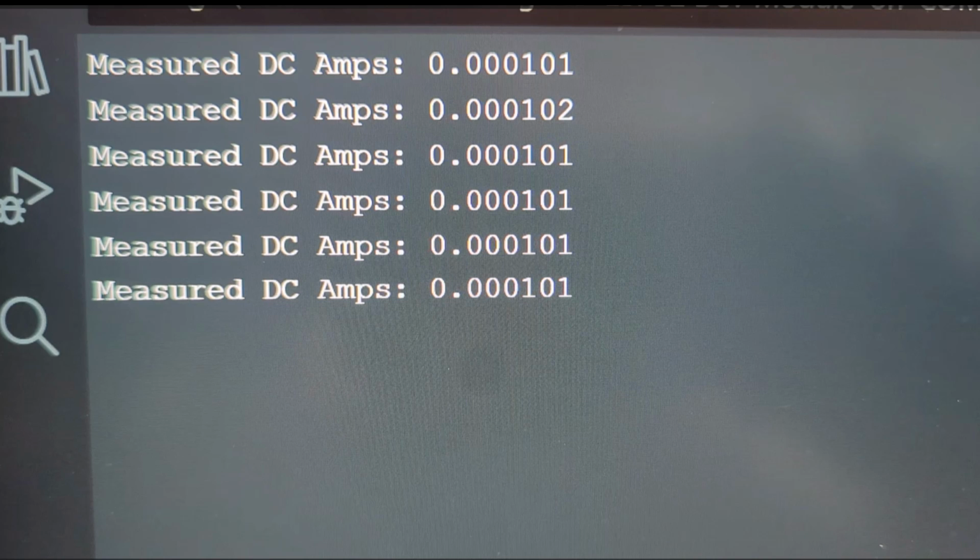We had to understand the actual resistance of our shunt that we're measuring. We have some filtering to take out noise, and we're not actually measuring that low-level voltage directly with the ADC. We're actually using a very high precision amp to boost that voltage up to a more measurable level. So that's how we're getting this great accuracy in this setup.